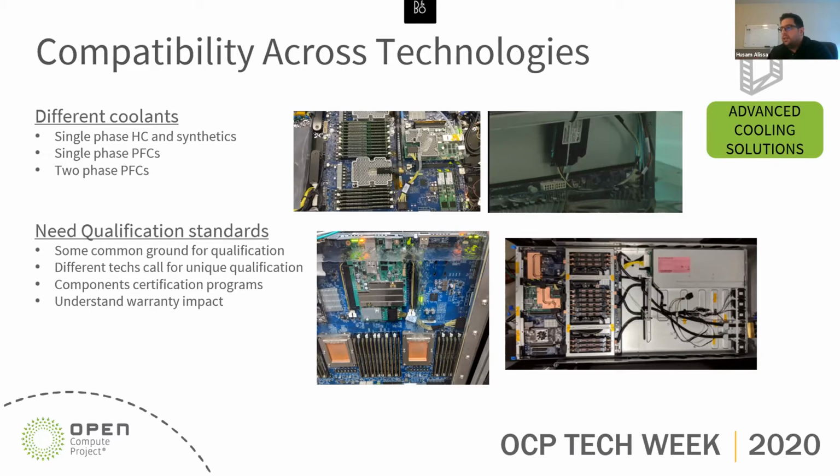Stability is at the heart of things, making sure the fluid doesn't have first-order or second-order compatibility challenges that can lead to short-term or long-term failures. Then there is the cost of the fluid, ensuring that it is sustainable and eco-friendly, and easy to handle in operation so it doesn't give a nightmare to the operator. And if it's a two-phase fluid, the boiling temperature needs to be right. The list can go on with many favorable characteristics.